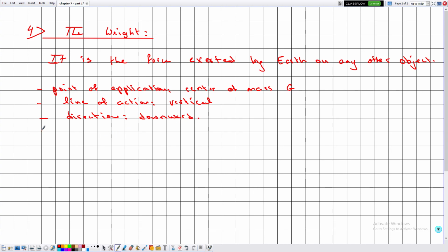Now in most cases we will be working in two dimensions. So any vector W is given by Wx i in the vector notation, plus Wy j. So we drop the vector and the magnitude W is given by the square root of Wx squared plus Wy squared, knowing that the unit of W is newtons. So the magnitude gives us information about the strength of the force. Moreover, the weight can be directly calculated if we know the mass and the gravitational field strength, because W is equal to m multiplied by g.